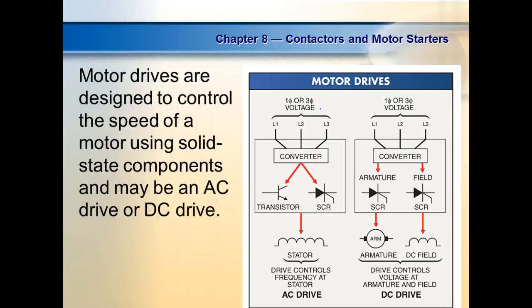We'll look at this later, but it's kind of weird. If you lower the voltage on the field, the motor speed goes up. If you raise the voltage on the field, it slows down. The other option is the armature, which is the best way to do it, but screwing with the field can cause problems on shunt motors or compound motors. You lose the field on a compound motor.